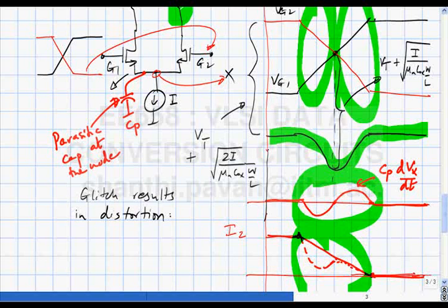One simple way of understanding it is to think about it the same way as we discussed rise and fall time asymmetry in DACs. Let's consider this to be a 1-bit DAC, so there are only two levels, either 1 or -1. Whether you put in a 1010 sequence or a 1111 0000 sequence, the mean must be the same, correct? This is a linear affair. And if this is linear, when I put many of them together in parallel in a thermometer fashion, that must also be linear. So it will suffice to analyze just this.